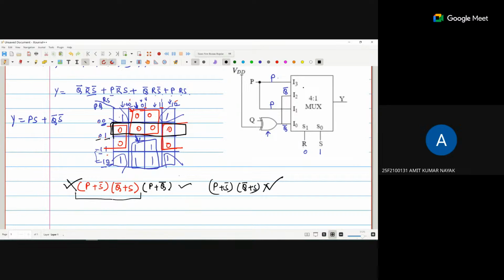Sir, in the last class, you did this multiplexer question in a different way. You said not to follow the K map, and for the upper row you take 0, 0, 0, 1, 1, 0, 1, 1. Yes, the thing is, if you write the equation, what is my equation? Y is S1 bar, S0 bar, I naught. Remember that? Now the representation is opposite.